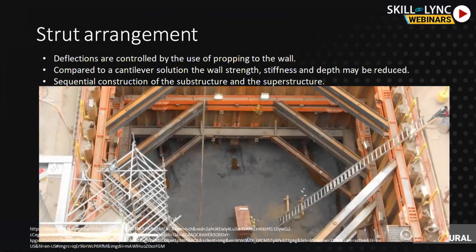So this is a general strut arrangement. This is just for a type of construction where only the corner struts are used. For other cases, there are main struts, which will be used when the length of the excavation is more. Generally, for strut arrangement, there can be pipe sections or UC sections used, and moreover these are reusable.